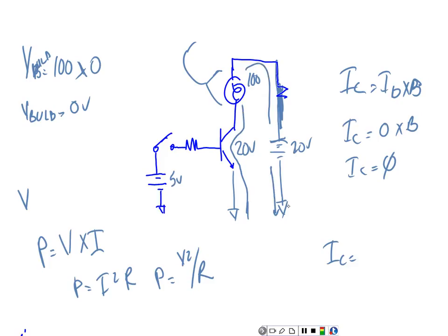So what we're trying to do is this circuit right here. I got a light bulb, and I got a switch. My transistor is the switch. We're not operating in the active region. We're going to operate this as a switch. Then over here I have a battery, a DC source, that's equal to 20 volts. If the switch is open, which means the transistor's cut off, which is what it is now, then how much voltage is across the bulb and how much voltage is across the transistor?